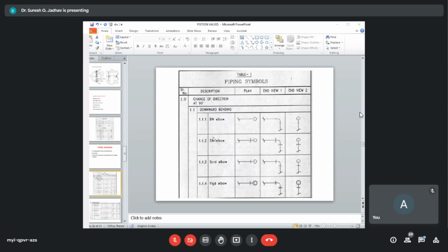The subject area of a particular drawing is hatched or shaded. Might be you hatched or shaded in your machine drawings. Here somewhere you drew the details and assemblies. When you cut the portion, then we can hatch or shade the particular portion. Might be studied in development of surfaces in engineering graphics or engineering drawings. The dimensional details of the title blocks are specified under the Indian standard IS 11665.